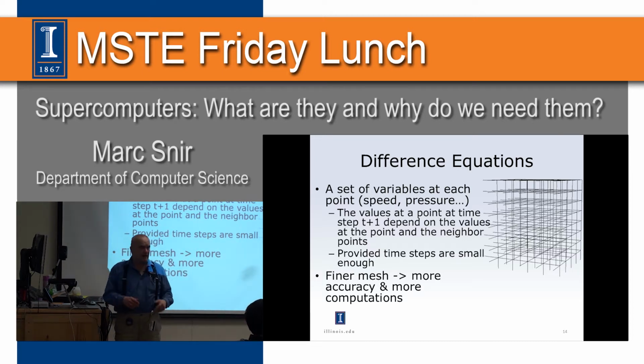And of course, the finer the mesh is, the more accurate your simulation is, because you are closer to the continuous case. But the finer it is, the more computations you will have, because you have more variables, and you have to go to smaller time steps when you go to a finer mesh.